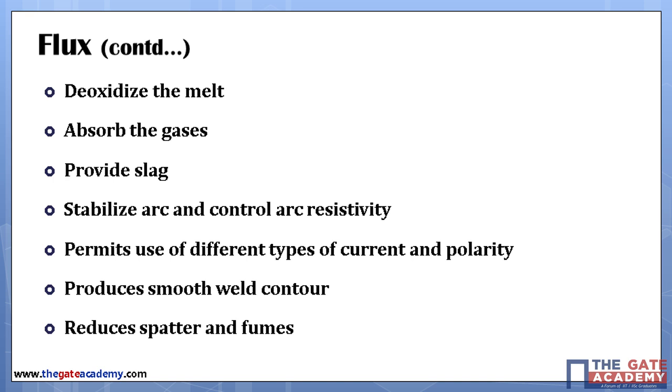Flux deoxidizes the melt. Do you think deoxidization of the melt is essential? Yes, obviously, because when the metal is heated to a higher temperature, the reactivity of the metal increases manifold. Okay, and that is why there are chances of contamination from the atmosphere, the gases surrounding the weld pool, and that is why the covering or the shielding of the weld pool is essential. And that is what flux does.